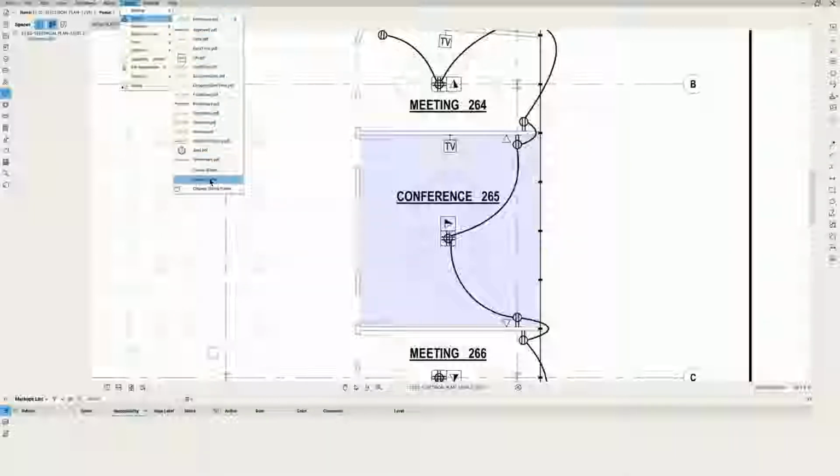Note that we can import stamps. So if somebody else in your company or organization or in another organization has created a stamp, you can share those stamps. So if the architect has some stamps he wants you to use, you could import the ones he's created, or vice versa. We can also change the stamp folder. I have mine in the default, but you could put those stamps on a network drive so everybody could get to them by importing them. Because normally stamps are located, if not out of the box, on your local hard drive.